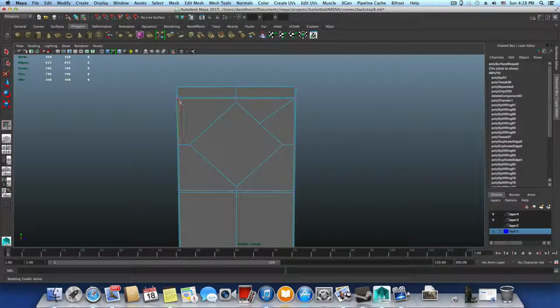Now, the problem with this tool is that whenever you click and then click again here and try to match the 50 point, like I'm doing, you won't always get this 50. It's not snapping to the 50, and this is very annoying. Therefore, what you can do is, after you created it, you will see that you have a new polysplit 1 and polysplit 2. This is the first one which we created, and polysplit 2 is the second one. So you can simply bring this back after you created them to object mode and add those values there.